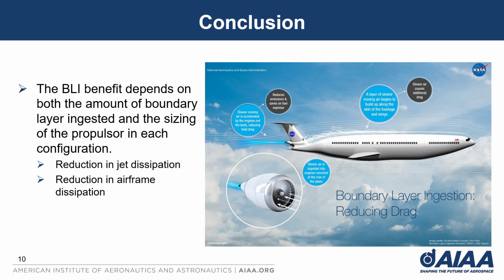It is shown that there is no unique way to compare BLI and non-BLI propulsion system performance for a given aircraft configuration. The BLI benefits depend on both the amount of boundary layer ingestion and the sizing of the propulsion in each configuration. It is reasonable to assume that configurations with higher ingestion will have correspondingly more considerable benefits.